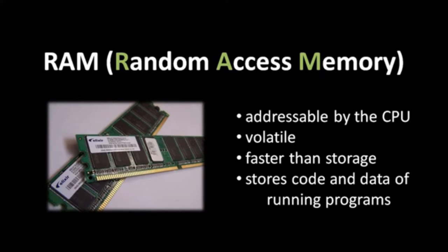A notable characteristic of RAM is that it's volatile, meaning that as soon as a RAM chip loses its steady stream of power, the content of the RAM gets scrambled. None of the bits can be relied upon anymore because, without power, they get flipped unpredictably. What this means in practice is that when you turn off your computer, the contents of RAM are lost nearly instantly. The next time the computer is turned on, the contents of memory start off in a total jumble as a bunch of random garbage. So this explains why the operating system must be loaded from disk every time you power on the system.